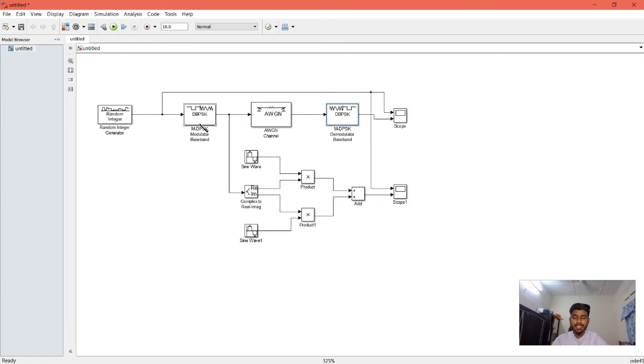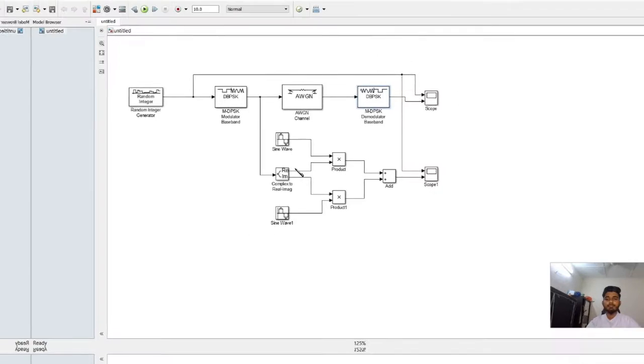This modulation process will occur by serial binary data from random integer block passed through XNOR gate, and the output is fed back via 1-bit delay. The resulting bit stream is applied to the balance modulator to produce DPSK signal.